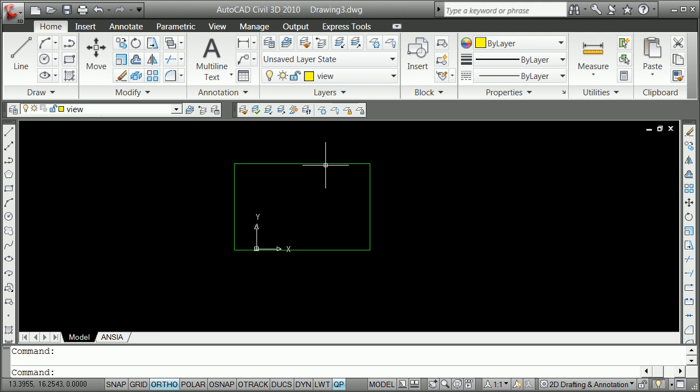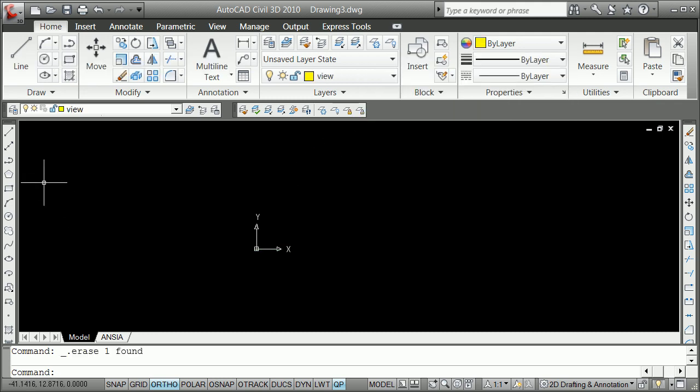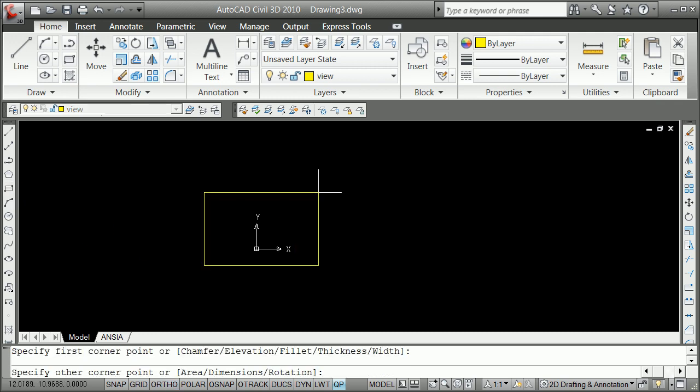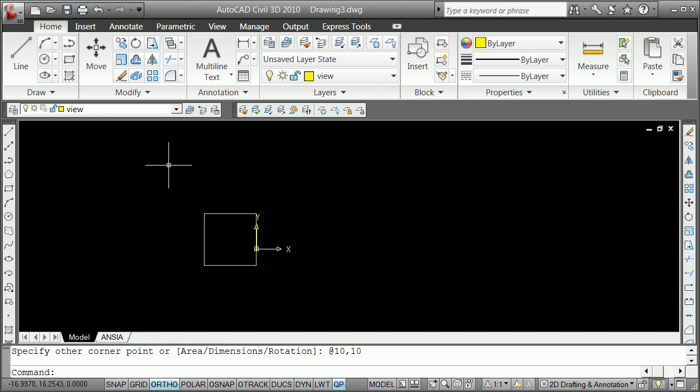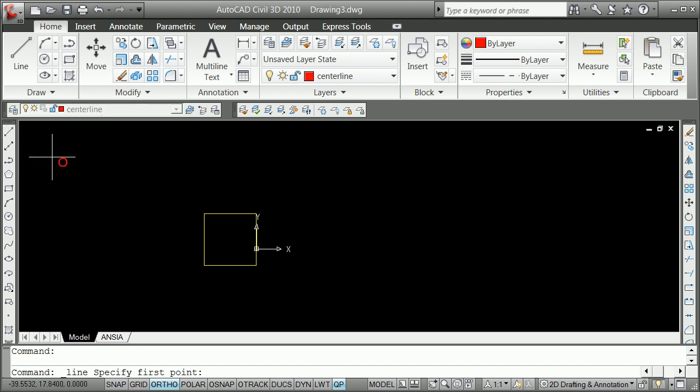So I'm going to take that box here, which I really don't need anymore. I'm hitting the delete key, and I'm going to go ahead and just draft my box like I did in class. I click on it once, I then type @10,10. I'm in a decimal drawing and it made the box. In class I said I want to put some center lines or some reference lines from the corner of the box to the corner of the box.